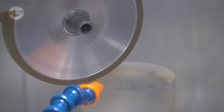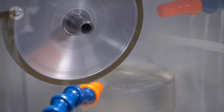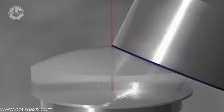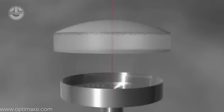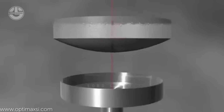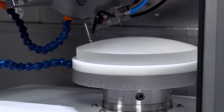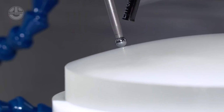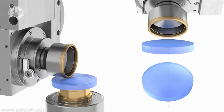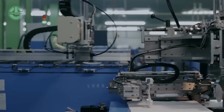They place a blank glass or glass disc on a rotating device where a curve generator can grind it with precision. The curve generator has a diamond cutter that carves out the lens with precision using CNC technology. To transform a blank into a convex lens, it grinds the edges to make them thin, while the center remains thick. On the other hand, a concave lens is shaped by seamlessly grinding from the thin center to the thick edges. This is called spherical grinding.